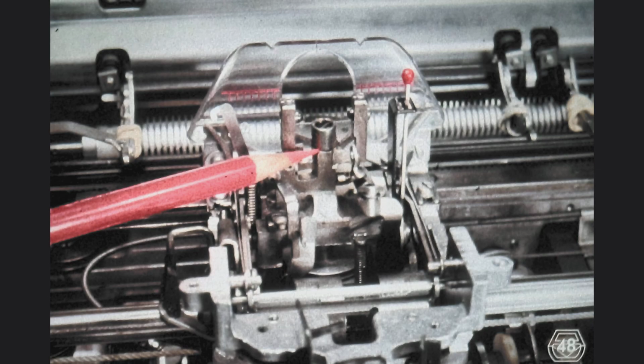In reality, this adjustment for the vertical play of the shaft, which holds the lower ball socket, called the rotate shaft, is an adjustment which has to be dealt with during the adjustments of the rotate tape mechanism. However, because it has an effect on the positioning of the element prior to the engagement of the rotate detent with the teeth of the element, or the skirt of the element, IBM considers this adjustment to be part of the fine alignment adjustments. Regardless of when we work in this area, we should make sure that there is a tiny bit of vertical play for this rotate shaft, not any more than 1/10 of 1 millimeter. But above all, we must be sure that no bind is created by our adjustment.